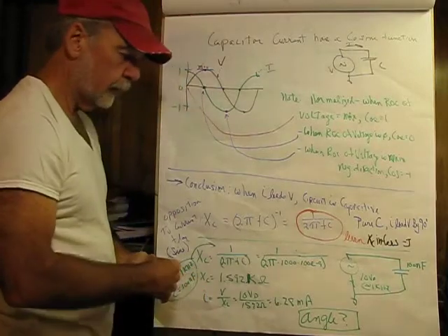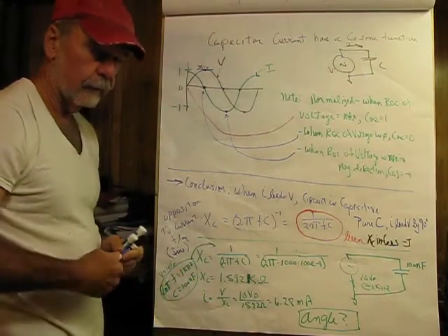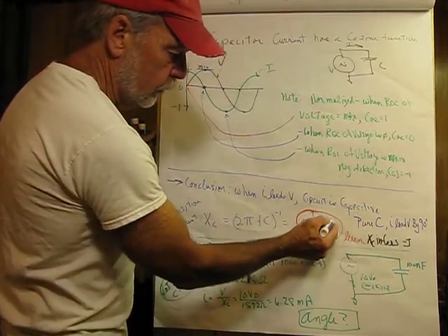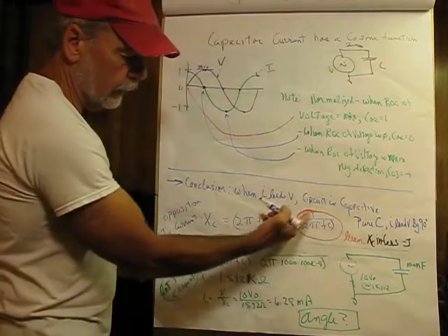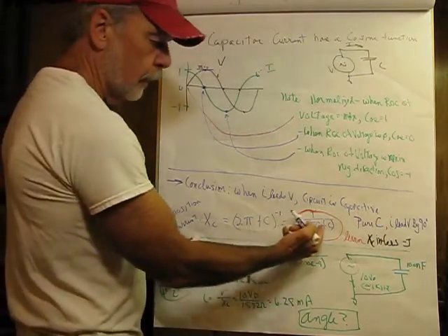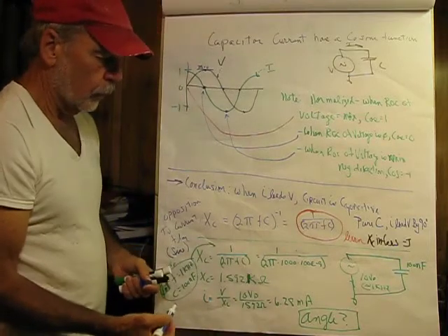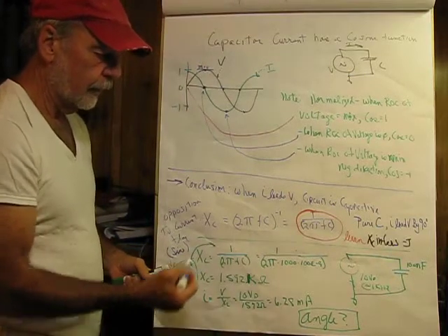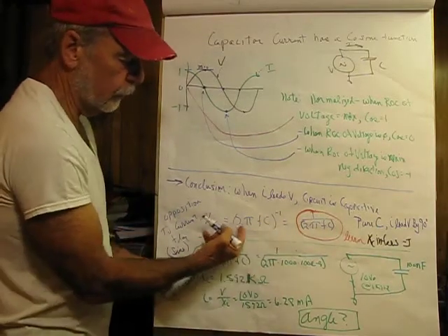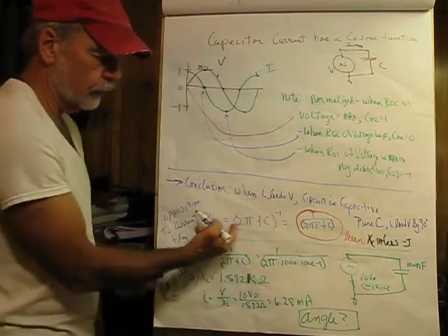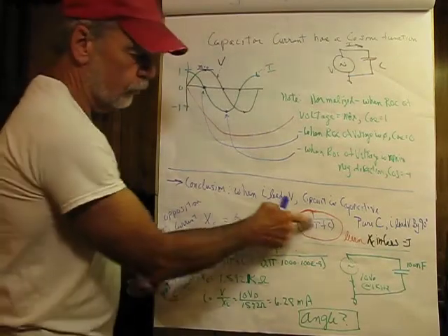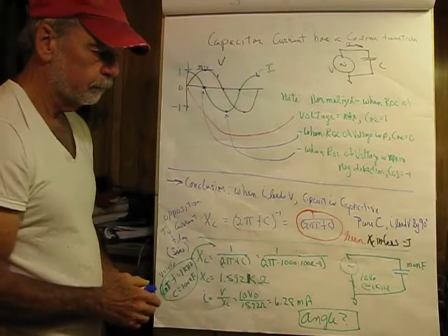And what you need to be very careful of if you do this on a calculator is that when you go to do the division, you parenthesize that, or you're going to end up with 1/2 times, by the rules of precedence, pi Fc. Also calculators have a -1 button on it. And if you just enter 2 pi Fc and hit the -1 button, raised to the -1 power, the law of exponents will give you this form and solve your answer.